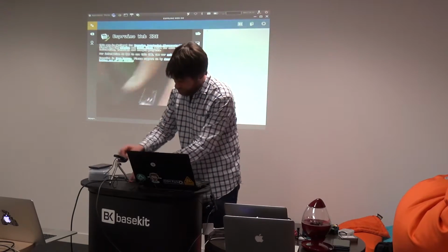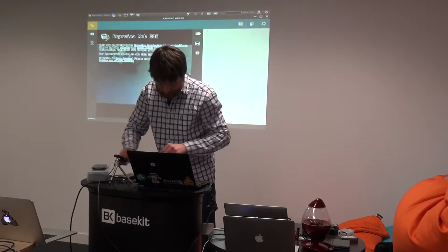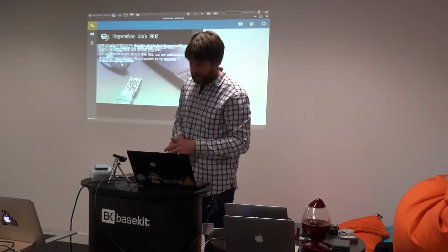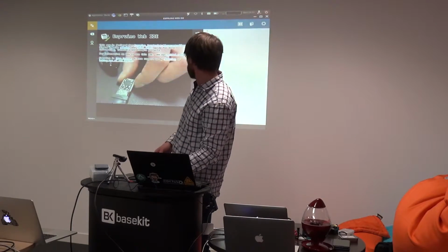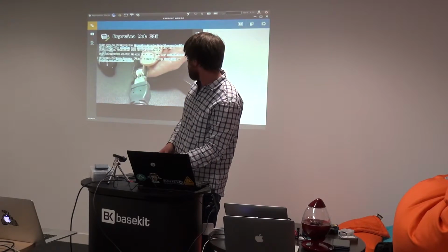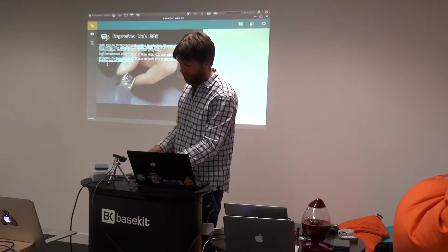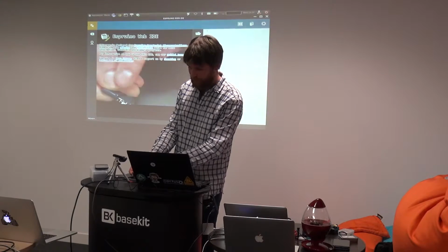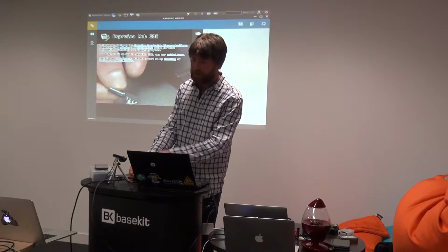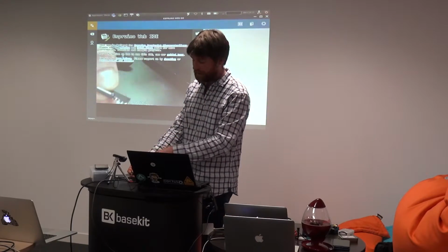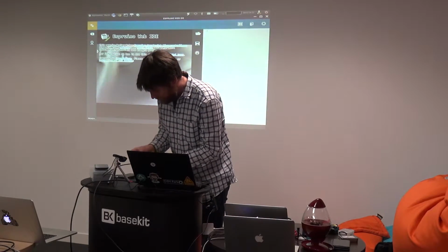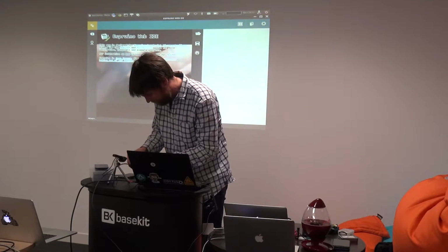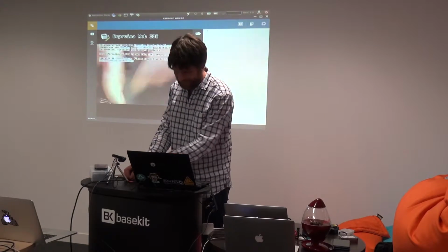Okay, so let's get it working. Okay, so this is a standard little Espruino Pico board. I've soldered a little power connector onto the back of it so I can show it running off a battery later. And I've literally just got a socket that I've wired a little vibration sensor onto, which is literally a spring with a wire running down the middle of it, and an LED. So I can just take this and plug it in, hopefully. If I can trap this properly.